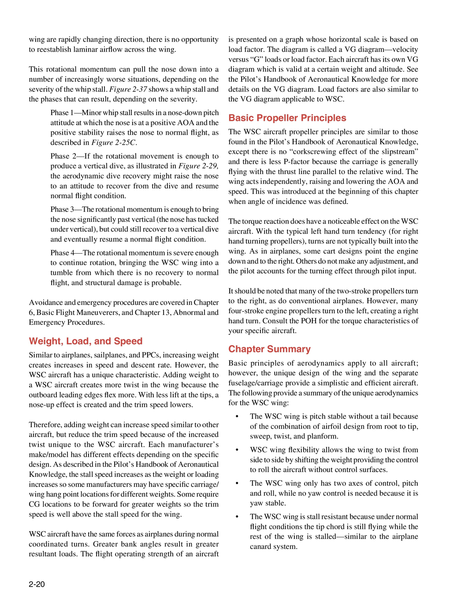The WSC wing only has two axes of control, pitch and roll, while no yaw control is needed because it is yaw stable. The WSC wing is stall resistant because under normal flight conditions the tip chord is still flying while the rest of the wing is stalled, similar to the airplane canard system.